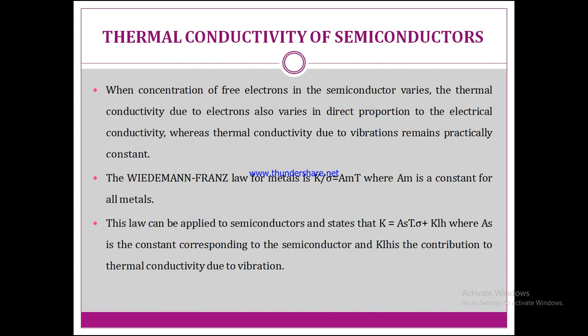Now, when the concentration of free electrons in the semiconductor varies, the thermal conductivity due to electrons also varies. It is directly proportional to the electrical conductivity, whereas the thermal conductivity due to the vibrations remains practically constant.